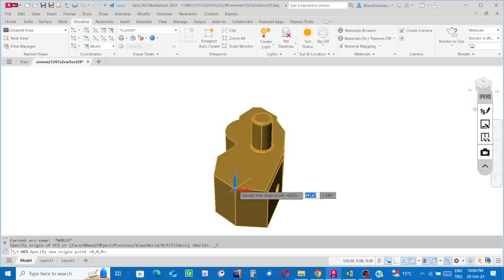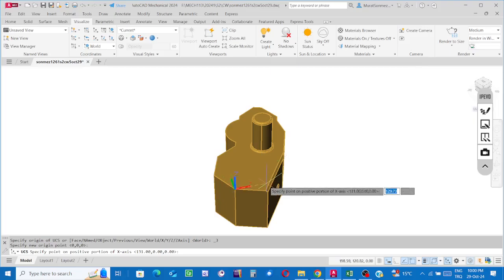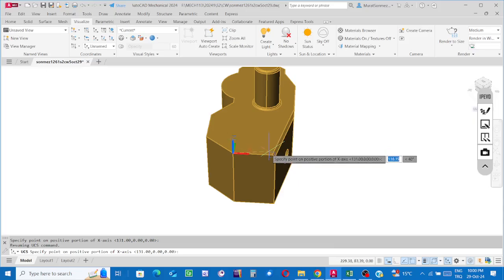It is this corner. While seeing the highlighted symbol, of course, make the click. And now the sense of the other coordinate axis is not important, because the important thing in this method is to coincide the x-axis along the edge. Along that edge, we have the point to mark.